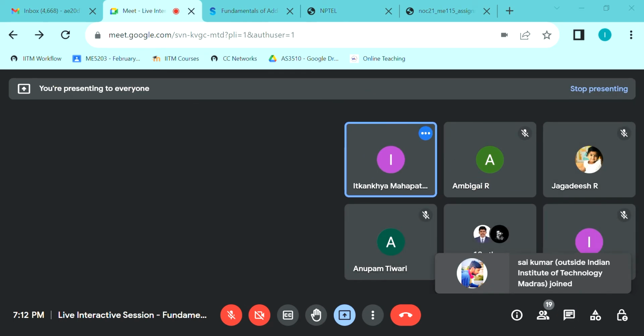Let's proceed. In an STL file, the surface of the CAD model is represented by triangles, as we can see here. While in the sliced file, we see the intersection between the horizontal planes and triangles. And the CAD file is the file which we usually get from SolidWorks or any processing software. This is the difference, and that is why the correct answer is the sliced file.